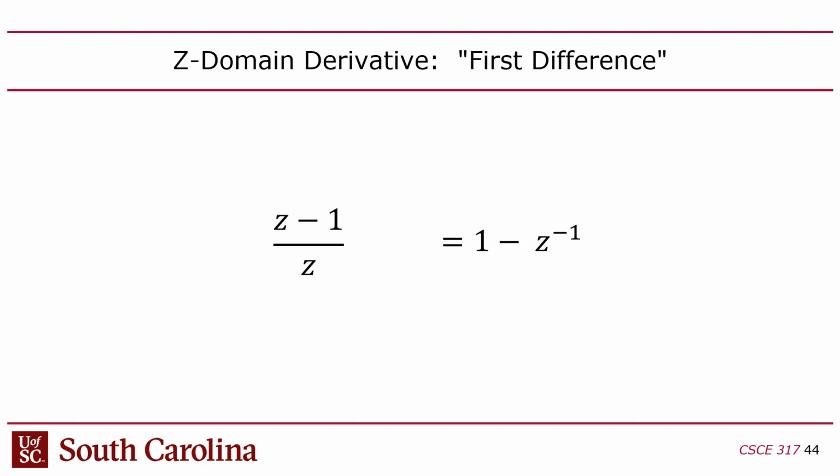Why is that? Well, you can take that and it's equivalent to Z over Z minus 1 over Z, right? Which is 1 over Z to the minus 1 power, right? What does that mean? It means that Z to the minus 1 power simply represents the previous sample. That's all it means. So in Verilog, if you have a register that causes a 1 cycle delay between its input and the output, Z to the minus 1 just means register, right? Essentially what it means.